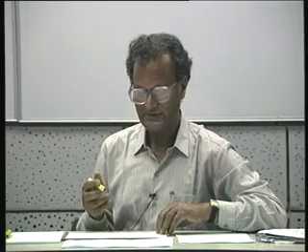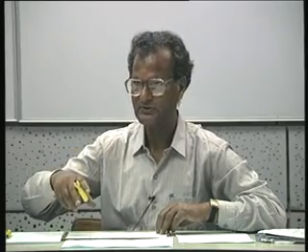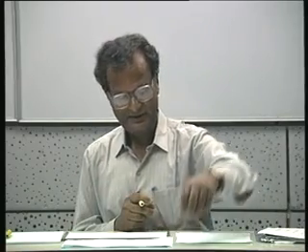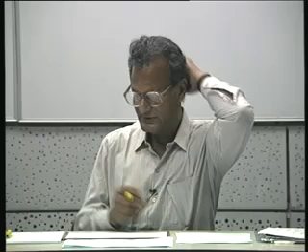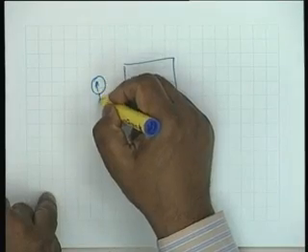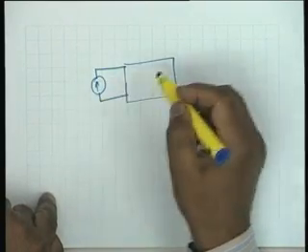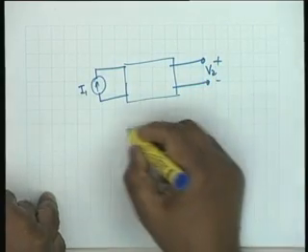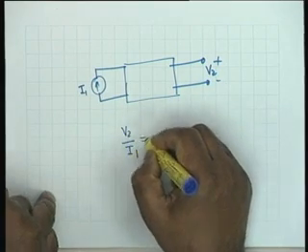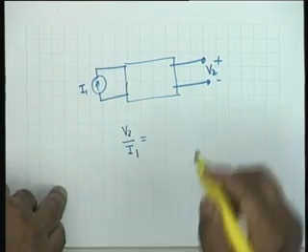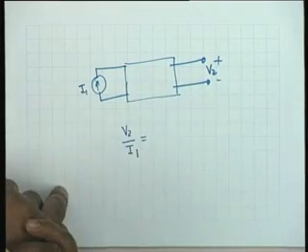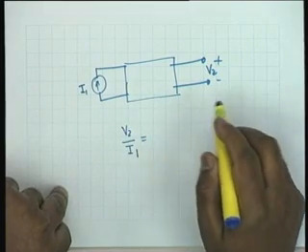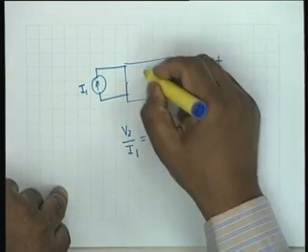A transfer function therefore relates the effect or the response at one port to the cause or the excitation at some other port. And you have already seen an example here. A current generator I1, and we measure the voltage here, V2. Then what is V2 by I1? It's a transfer impedance, okay? And how is it related to the parameters of this circuit? Which parameter? Z12 or Z21? Z21, okay? This is described by the Z matrix. This is Z21.